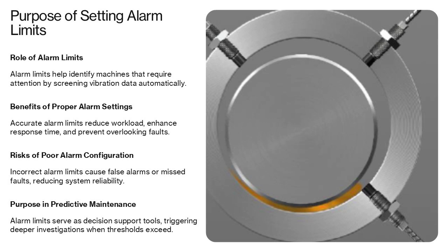From an engineering perspective, alarm limits are not intended to provide diagnosis on their own. Instead, they act as a decision support mechanism that triggers deeper investigation when predefined thresholds are exceeded. Poorly set alarms can be just as harmful as having no alarms at all.